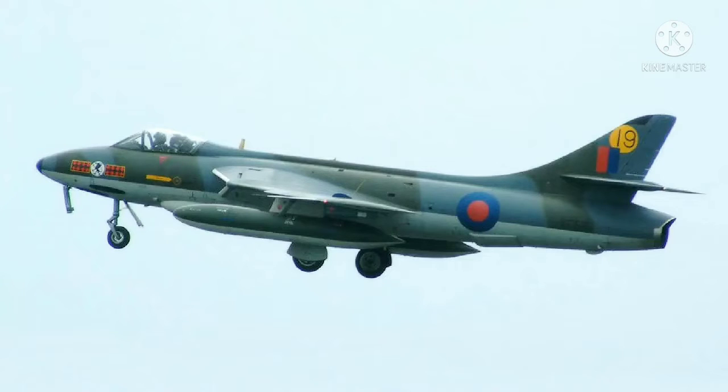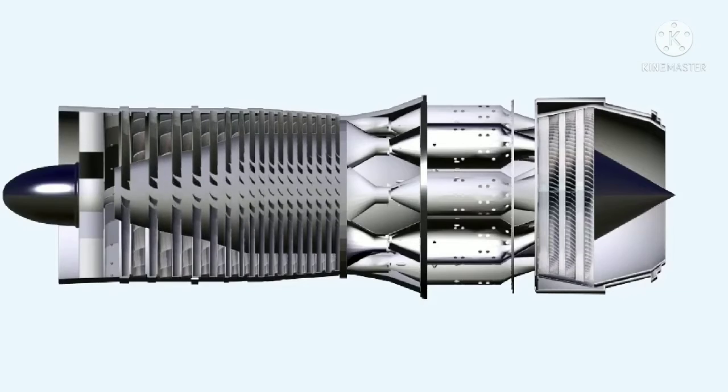This type of engine was for a long time considered to be the most useful where an engine with a small frontal area was required, such as in fighter aircraft, where a high forward speed was the main criterion. There are, however, problems with the control of the smooth flow of air through the engine throughout its rotational speed range. More of this later.